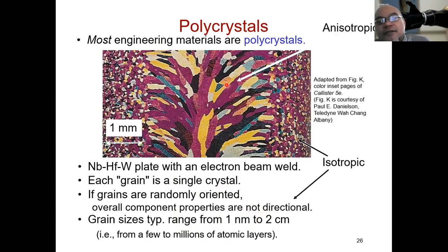But the one in the middle, or the one like here, has a different orientation in one direction compared to another direction. We call that kind of crystal anisotropic. Iso means the same, and tropic means direction. So isotropic is when they have the same property in all directions. Anisotropic means not isotropic. Maybe the Young's modulus will be larger in one crystal direction compared to the other crystal direction.